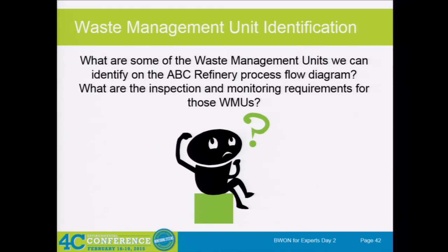The interesting point is, you're in Texas, so you know MSS, right? Or you're familiar with it, I'm not sure if you've dealt with it. Under BWON, you don't have to do anything with the vent on the vacuum truck to consider it controlled. All you have to do is quarterly visuals and annual NDEs. When you do those, you need to make sure there's liquid in there, because monitoring an empty vacuum truck may not be the best indication of whether or not you're leaking.